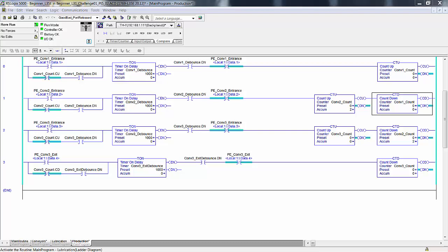Other than the obvious, conveyance from A to B, entrance of conveyor 1 to exit of conveyor 2, there are many different logical modes for controlling conveyors. We will examine just a few of many. The beauty of the programmable controller is that you can write routines for many different modes and then logically select which mode best suits the upstream and downstream conditions.